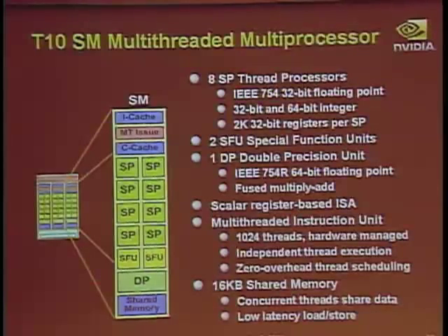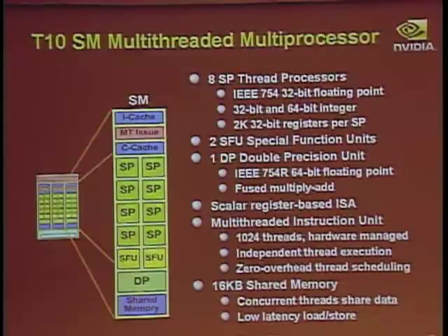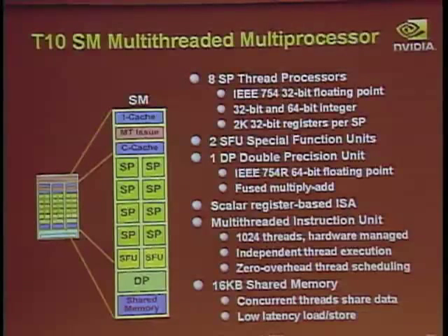You say add R1, R2, R3, let's say. That means that you can broadcast the register number to all the thread lanes, right? It's like a SIMD. So that's like a SIMD vector internally, but you don't have to think of it as a SIMD vector as a programmer. I think that's the advantage here, is that here you have per thread individual description. You're thinking and describing what happens on a per thread basis. Hardware under the covers is doing all this SIMD stuff for you and all this vector stuff for you.